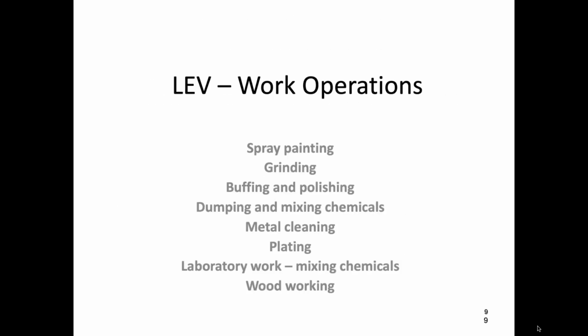Okay, so here are a few operations where you might use local exhaust ventilation. Spray painting, for instance, spray booths. If you have ever seen a professional automobile body shop where they do a lot of spray painting of vehicles, they have spray booths. And these spray booths have filtration. They have enormous walls of filters with fans behind them, continuously pulling air so that the worker can spray the paint onto the car and have all of the fumes and the material from the paint pulled away from him. On the other side there is an enormous wall of filters, so the fresh air coming in is filtered before it gets into that space.